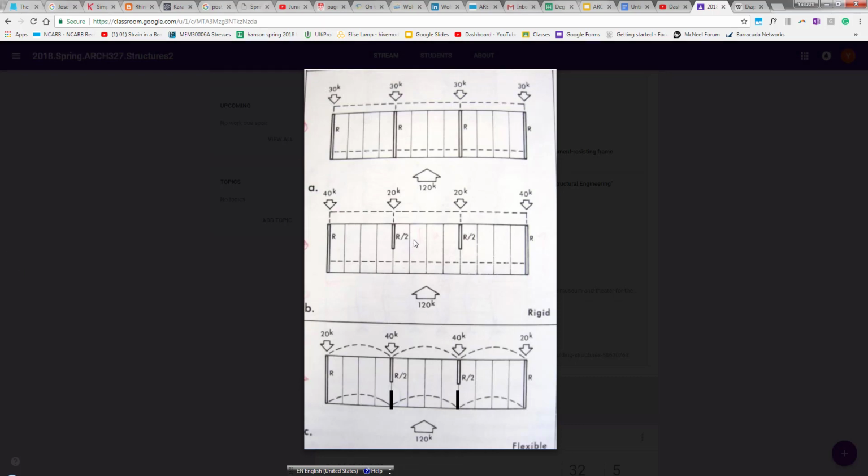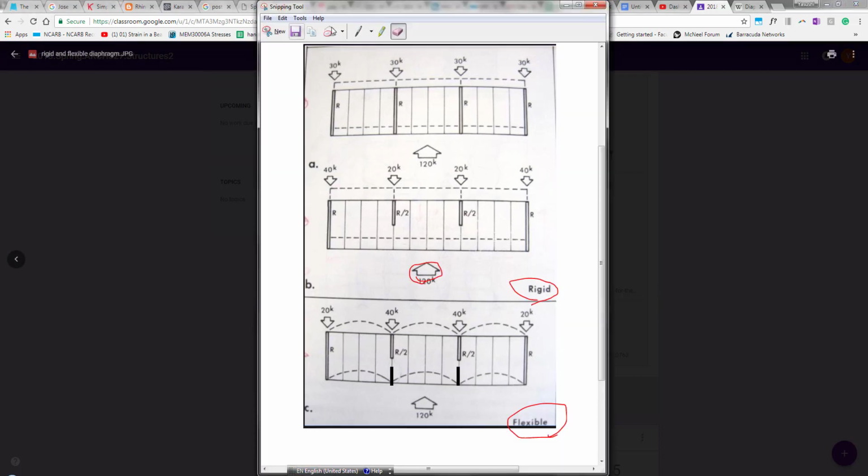So this one is very diagrammatical, and it's only trying to look at the lateral force this way. That's why we're only showing the wall in this direction. But just so you know, this doesn't really work with a lateral force coming from this way, it doesn't do anything. This is just for explaining this direction. But that's important. Shear wall is kind of like a beam that's flipped vertical.